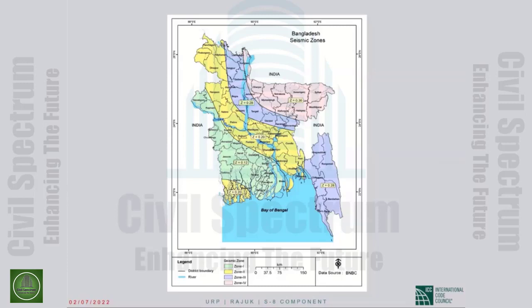Any detailing from collector to shear wall? So, the detailing requirement for collector to shear wall. So it's just a general question. Are you going to go over that detailing? I don't know that there is any specific detailing requirement for collectors. We have to have the reinforcement that is needed, and then the overstrength factor on the connection. But there is no special detailing requirement that I'm aware of.